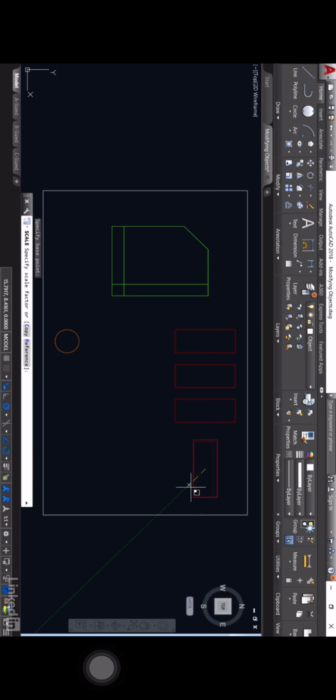Now, as soon as I do that, you can see as I drag, I can make that bigger and smaller freehand. I'm going to specify a scale factor of 1.5 and enter. And you can see it's now 1.5 times bigger, and the original rectangle has disappeared. Be aware when you scale things, you're scaling the original object, so there's nothing left behind. It's not like copy, for example. You can leave it behind if you wish, though.